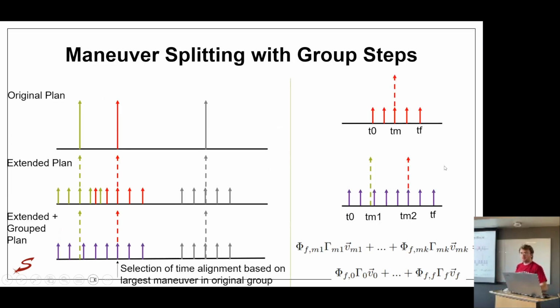The issue there is that you have green and red just lower than the main one on the second line. Yes. So in this one, the time between these maneuvers is less than the refill time, so that plan would not be physically possible with the actuator system. In which case you can just combine the propagated dynamics linearly in the constraint equation and rerun the optimization. It's a linear program which runs quickly.